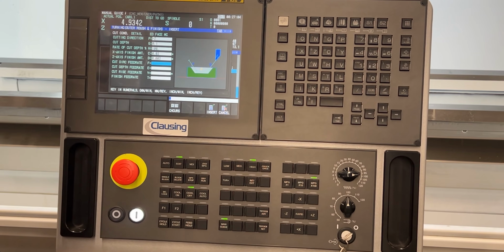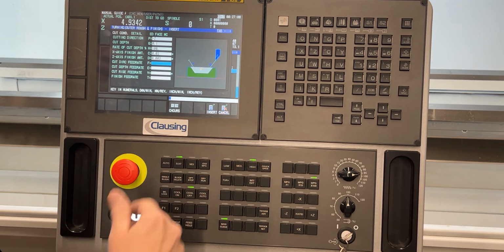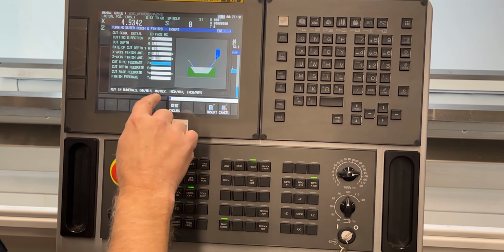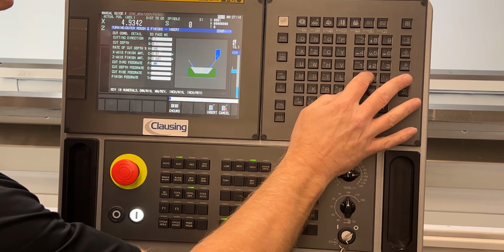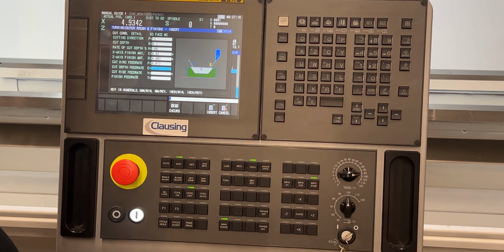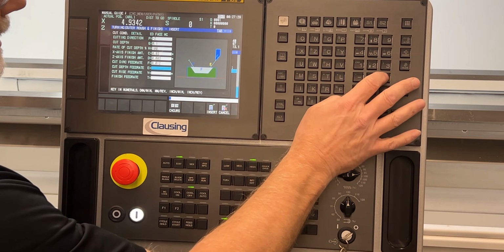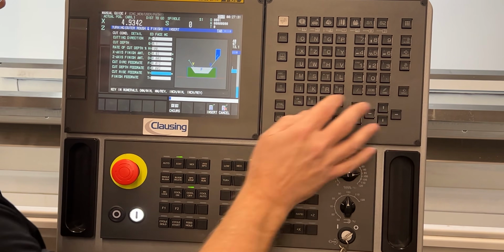The other thing that it asks for is my different feed rates, of which there are 4 in there. The first one is my normal cutting feed. So let's put in there 12 thousandths per rev. My cut depth feed rate is if I have a re-entrant shape. So instead of diving the tool in fast, I'm going to slow that down if I had it.